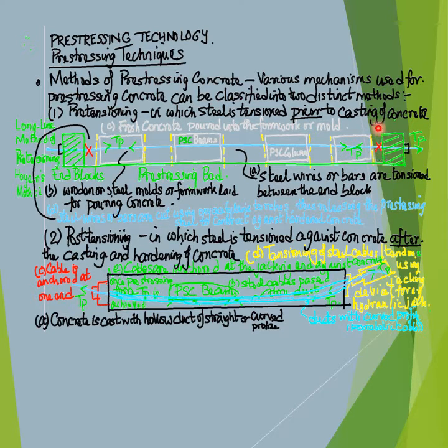After the pre-tensioned steel wires or bars are cut at the ends, thus generating a pre-compressive stress in the concrete elements termed as pre-stress, and a corresponding equilibrating pre-tensile stress due to the pre-tensioning force capital T subscript P in the steel wires.